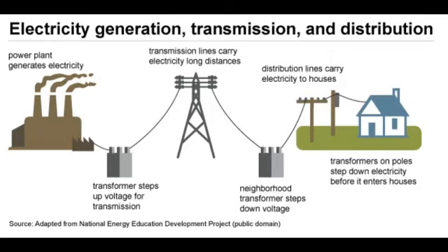Okay, this slide shows you how power gets to your facility, the power lines into your facility or your home, coming from the power generation plant where they burn coal or gas to make steam, to turn generators, to generate the electricity, which is very high voltage when it leaves the plant, and it is stepped down through transformers by the time it gets to your facility, where you hear typically about the 120 volt or 240 volt. And in larger facilities, commercial installations, 480 volt, three-phase.